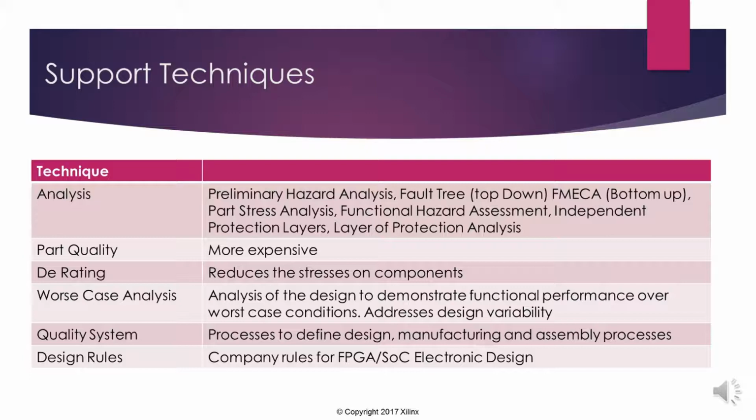We also need a quality system, to tell us how to actually design, manufacture and assemble these mission critical boards, and that quality system is going to be aligned with an international quality standard such as AS9100 or the ISO standards. And then as well, we will also have internal design rules that tell us how to design our boards, how to design our FPGAs, how to design our SoCs. So they will go down to the level of code rules.